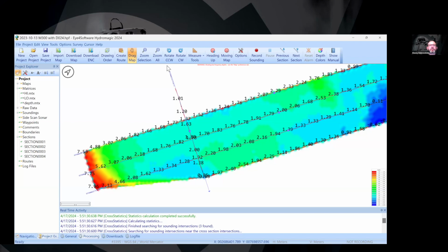Only in that case, you can fly in PPK mode and have a kind of Linux file logged in the memory card of your payload. In theory, you can fly with a DJI camera or DJI LiDAR together with the Echo Sounder just to have the file logged during the flight. As a possible solution, you can use absolutely any PPK receiver, an additional receiver on your drone.